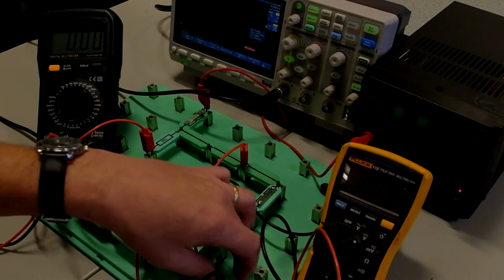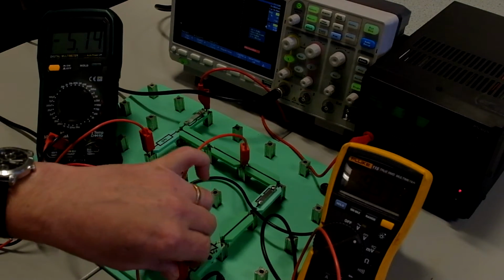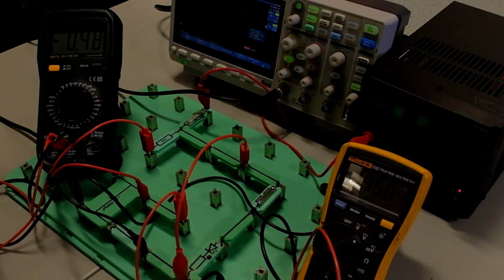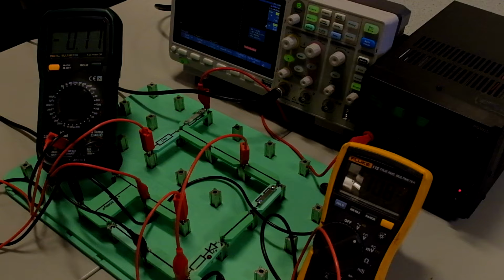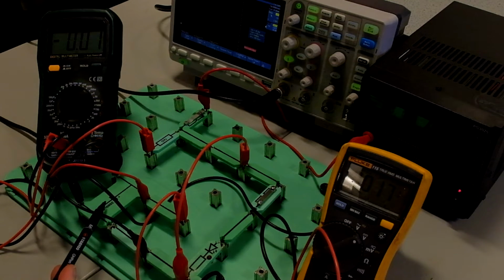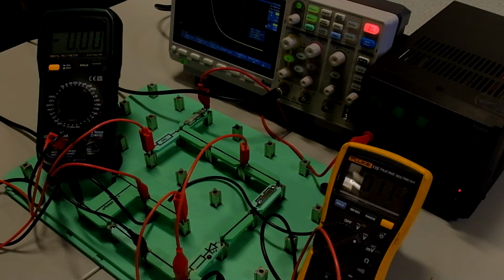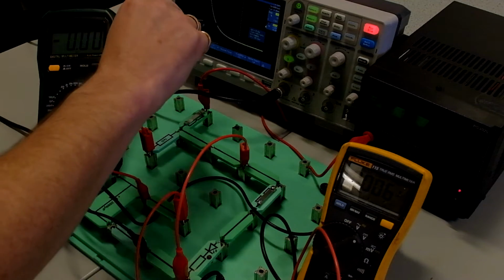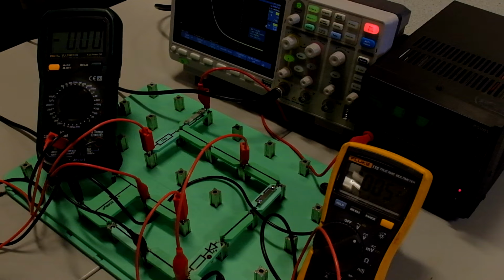So what we're going to do now is connect a wire across R and C to discharge it. You can see the voltage is dropping rapidly. Current is now in the opposite direction. Why is that? Current is now flowing out of the capacitor through the resistor, being dissipated as heat, and eventually all the energy stored in the capacitor will be dissipated as heat coming out of the resistor. What we can see now is an exponential curve coming down from 10 volts. We should be able to see a 63% drop from 10 volts within 2 seconds, so down from 10 volts to 3.7 volts within 2 seconds.